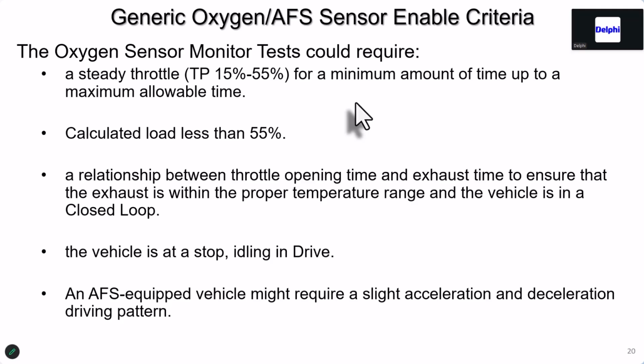and you would assume that the exhaust was hot. Well, the PCM does that for you, and I'll show you in a video later how the PCM does that. And all cars are doing that. They're inferring that the exhaust is hot. And in global OBDII now, in CAN cars, you can see the inferred temperature of the CAT on the scan tool. We'll see that a little bit later.